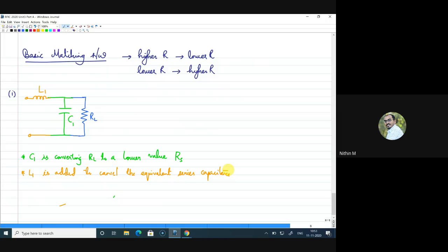Yeah, it is because of frequency dependence, because we will be designing a circuit for some particular frequency. Now, I need to make sure that there should be some possibility for us to tune with the frequency also. So, adding a resistance in parallel, or adding a resistance in series, will provide the same impedance for all frequencies. There is no frequency dependence, first of all.